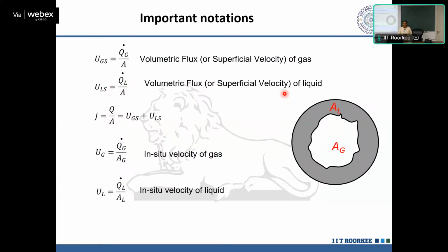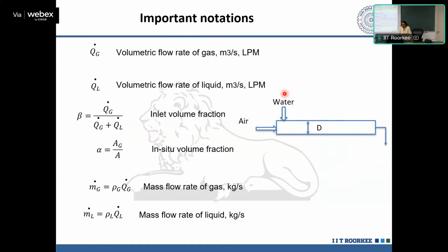So now we can draw the flow pattern map from the last tutorial example, right? And there is another basic piece of information, this quantity beta. Beta is the inlet volume fraction. Inlet volume fraction is how much of one phase is being injected in the test section. Let's say we want to calculate from the last tutorial the volumetric flow rate of, let's say, toluene, our dispersed phase in the tutorial.